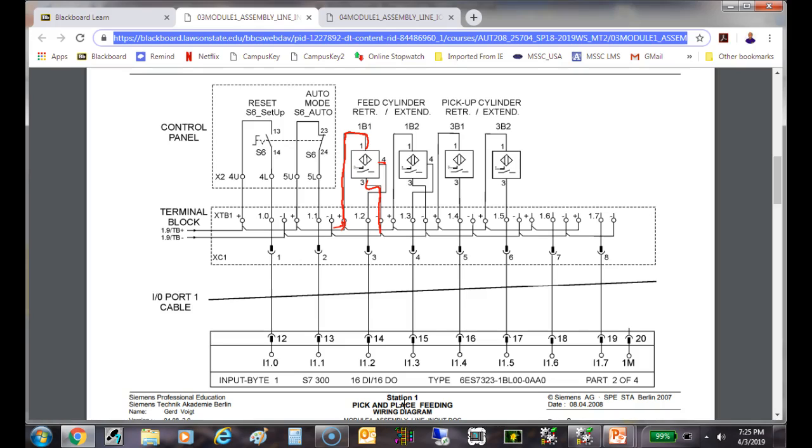So we're using a Siemens S7 314. Now you can't configure its ports like you can the Allen Bradley. So this guy runs sinking inputs and sourcing outputs. And look at the numbers. And we'll look at the color code too.